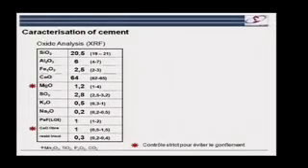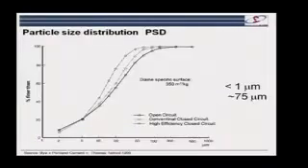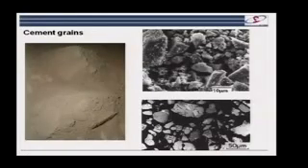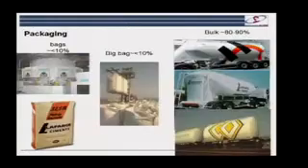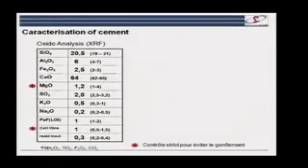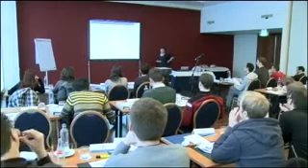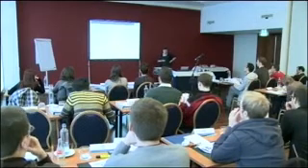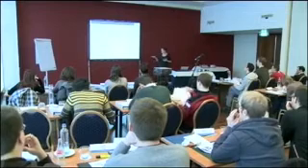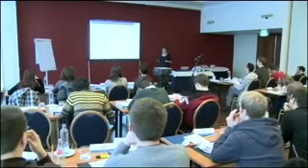Right, so we've got our cement, and we've got these different phases, C3S, C2S, etc. Well, of course, we want to know how much of these different phases there are in our grey powder. And up to quite recently, this was really a problem, because typically when you check the composition of cement, you do an X-ray fluorescence test, which tells you how much of the different elements are present. And then these elements are transformed to oxides, and they're listed in a table like this.